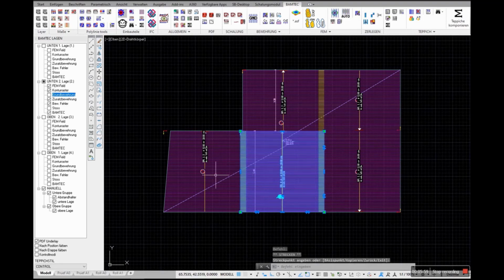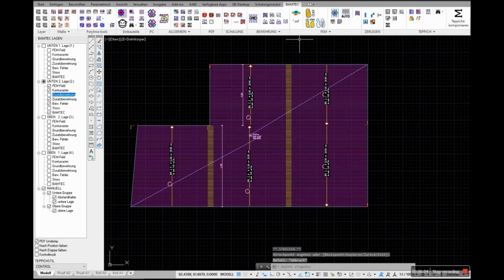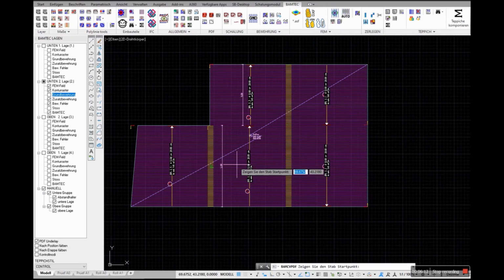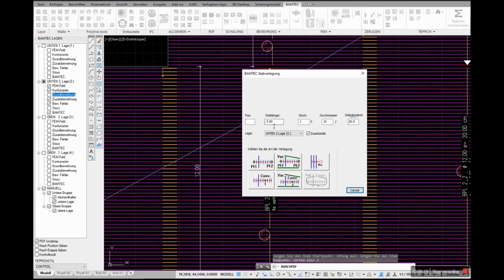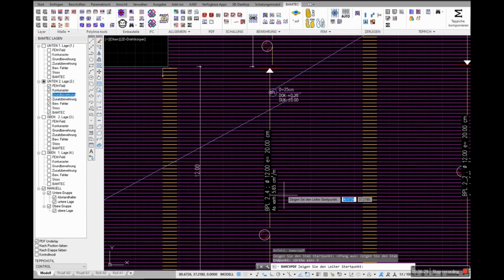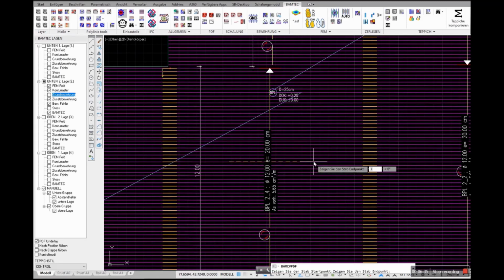The position designations you can see in the plan are freely chosen by us. We've decided to use the layer and the number of the carpet as well as the basic reinforcement for easier testing with the structural engineer, and thus also the resulting cross sections. Now we've got a simple command to add additional reinforcements. The most frequently used forms and variations are already here. Depending on the active layer and layer control, the bars are placed in the right direction.